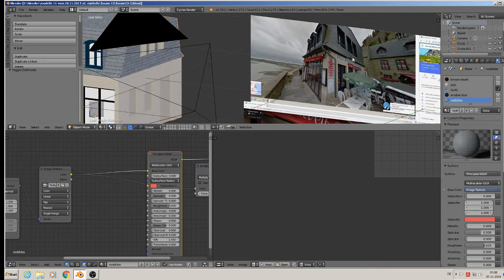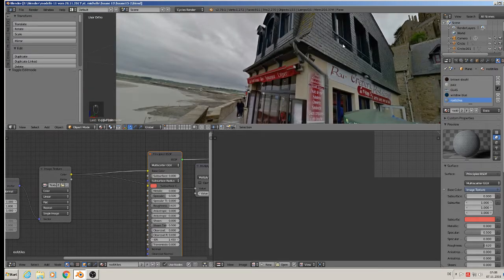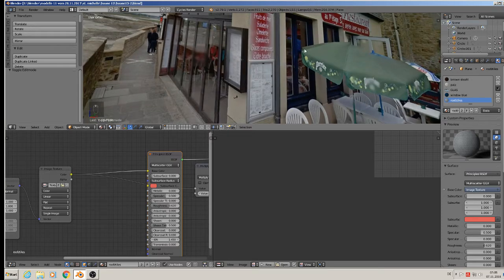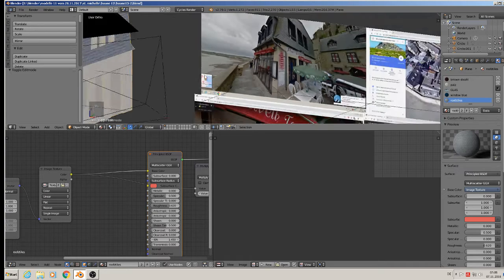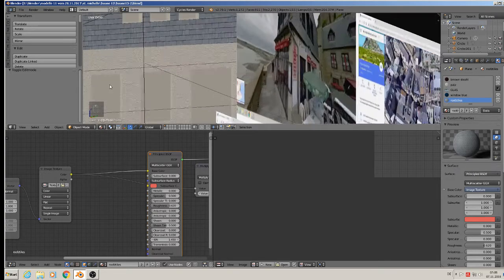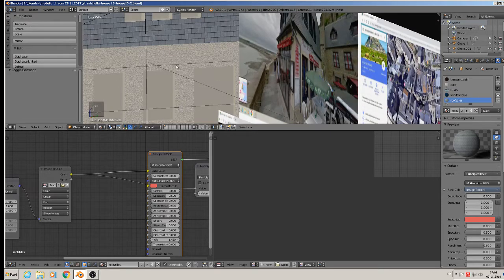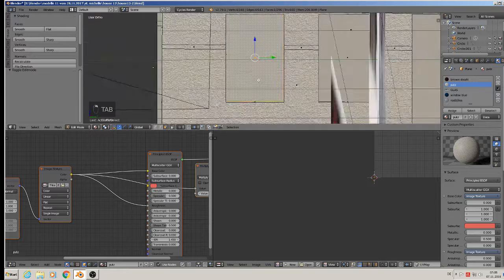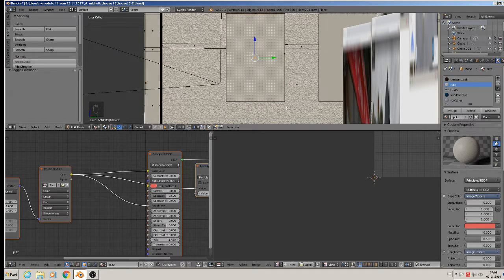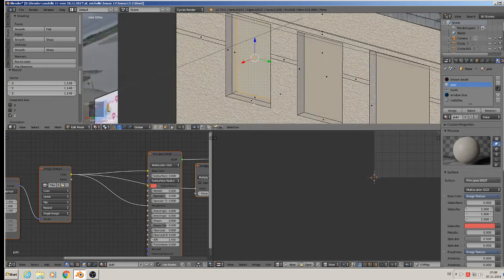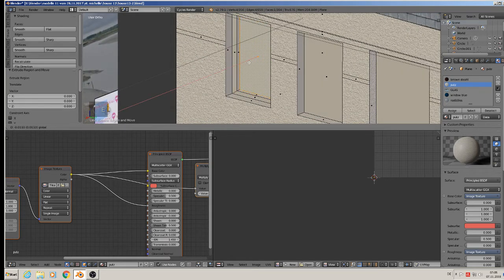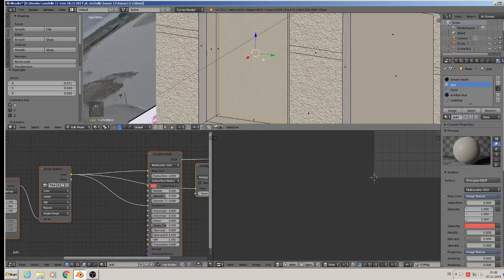So what we next have are the windows. Simple ones with only one in the middle and this bluish color. So we can take here one of them, the windows, extrude, scale to get the outer frame, scale set, extrude and go back, and then only the middle part is needed.